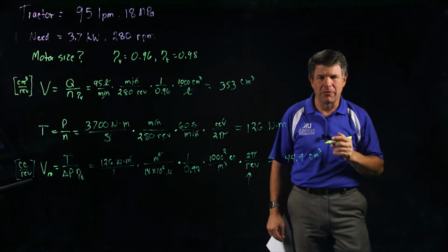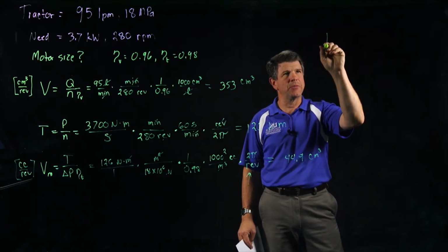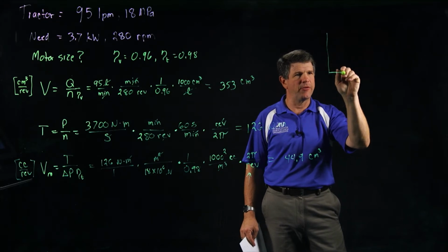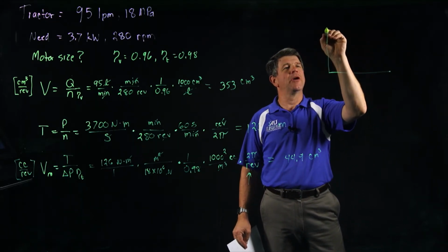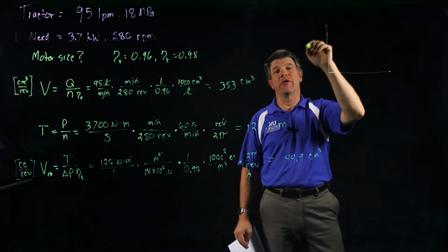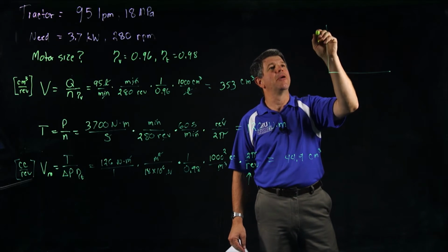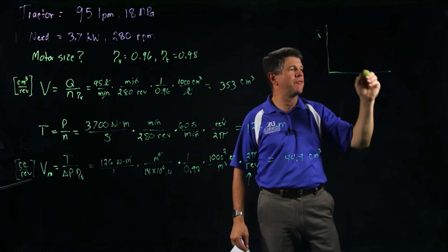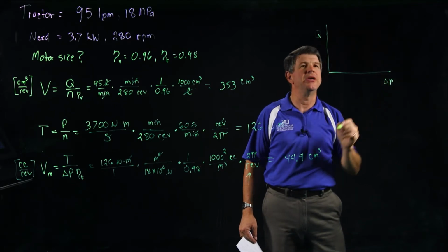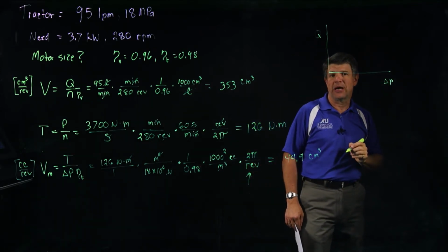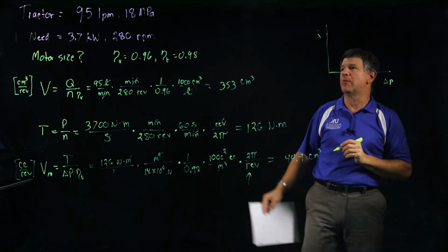But now we've got to be real careful about this. We're going to hit this more as we talk about performance of valves and things like that. But we're going to look at performance curves of the hydraulic system. You're going to get these in the lab. We're actually going to calculate these things. And we're going to calculate or measure the flow versus the pressure available, flow versus the delta P for a system, okay?